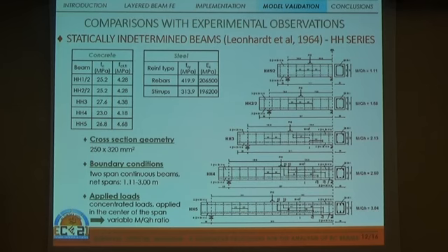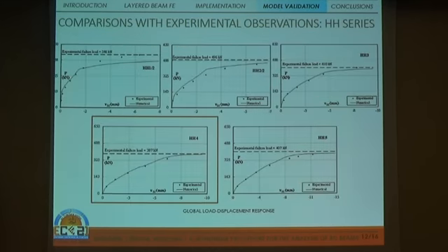The specimens differ in the different values of the ratio between the applied bending moment and the shear force, which is a very critical parameter affecting the shear capacity of the beams. The same modeling choice already described has been adopted, but in this case the symmetry has been exploited and consequently only one half of the beam has been modeled.